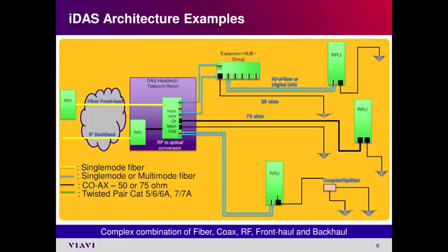But what happens in a typical scenario, and not necessarily the only way, because different DAS vendors have developed different kinds of DASs, you take a signal, an RF link coming from a regular macro base station, and send it through conditioning equipment where you drop down the signal from 43 dBm to a much lower level, which is then fed into the DAS head-end unit.